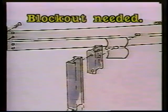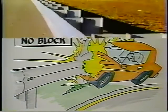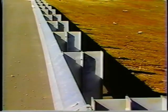Many early guardrail designs were not blocked out, and this caused some problems. When a vehicle hits a rail that is not blocked out, the impact will often flatten the rail. Instead of sliding along the face of the rail, the vehicle will penetrate beneath it, snag a wheel on a post, and spin out onto the roadway. The addition of the block out will help prevent this problem in most situations.